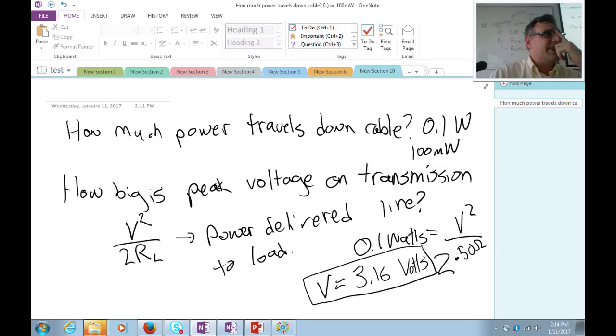That's a good, useful number to hang around, right? Because what if I was transmitting 1 watt down a cable, a 50 ohm cable? You'll hear we'll probably use lots of examples with 50 ohms, because that tends to be what RF engineers use as their reference value for cables. 75 ohms as well, but generally in microwave engineering it's 50 ohms at the higher frequencies.